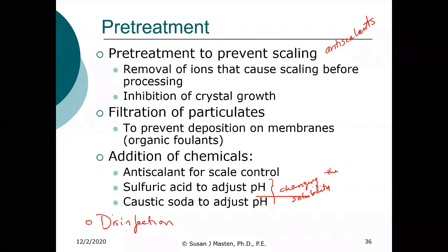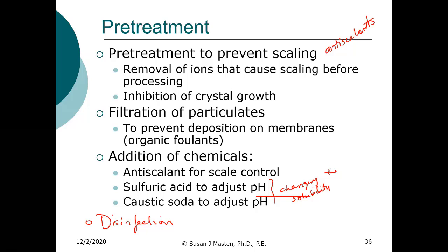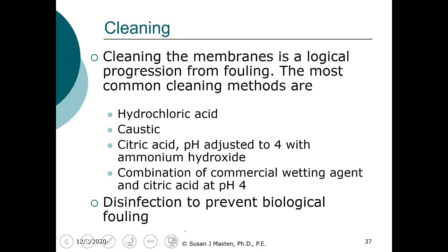The other thing, which isn't here, is disinfection. As Austin just mentioned, here you're trying to kill the microorganisms to prevent excessive biofilm accumulation on the filter itself. It's one of the reasons in the engineering building, if you go to the lab, there's the DI water and there's the regular tap water. You don't drink the DI water, and it's because of the chemical disinfectants. They used to use formaldehyde. I'm not sure if they're still using it, but they disinfect in order to prevent biofilm growth on the membrane itself.